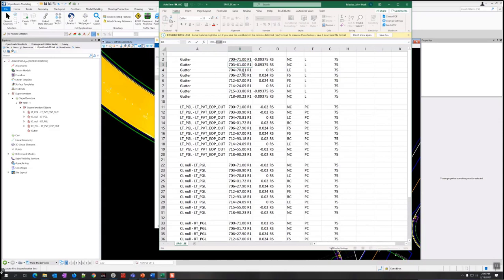So I'm just going to make it 10 less. Let me just copy this one. It's 704, not 703. Paste it here. Then I'm going to change the 70.81 to 60.81, so it's 10 foot. I'm going to do similar over here. I'm just going to copy this value at 0, paste it down here, and then set this to add 10. So I'm going to say 34.09. And that should do it. Yes.